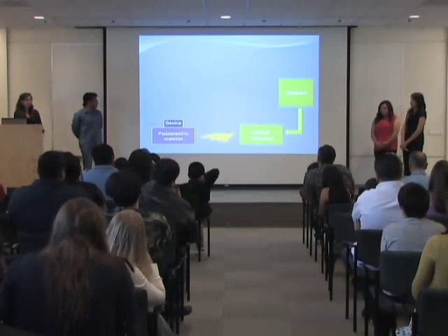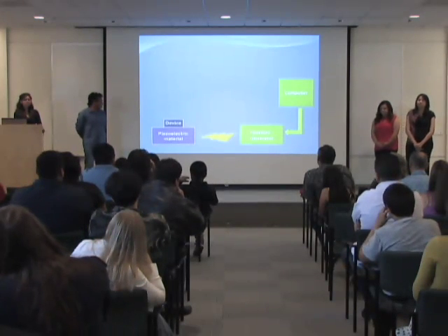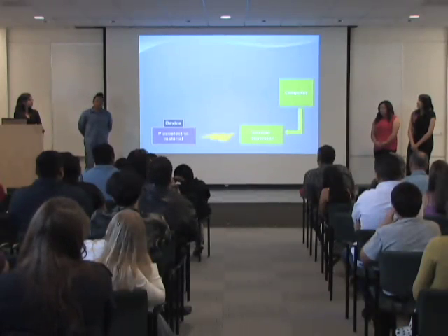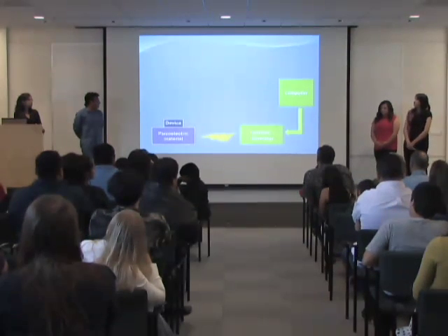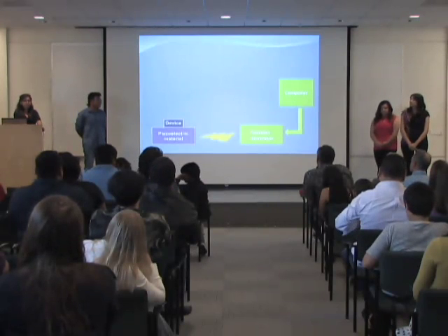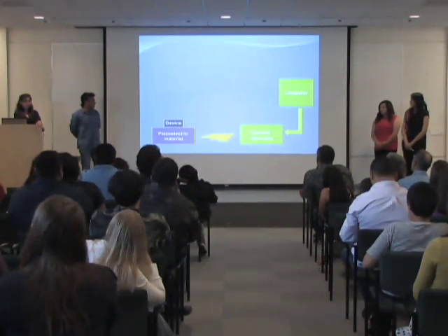This is applied towards a piezoelectric material. The reason being is piezoelectric material has certain properties in which, when voltage is applied to it, it deforms. The microcantilever device is set on top of this device. The piezoelectric material deforms and helps the device oscillate.